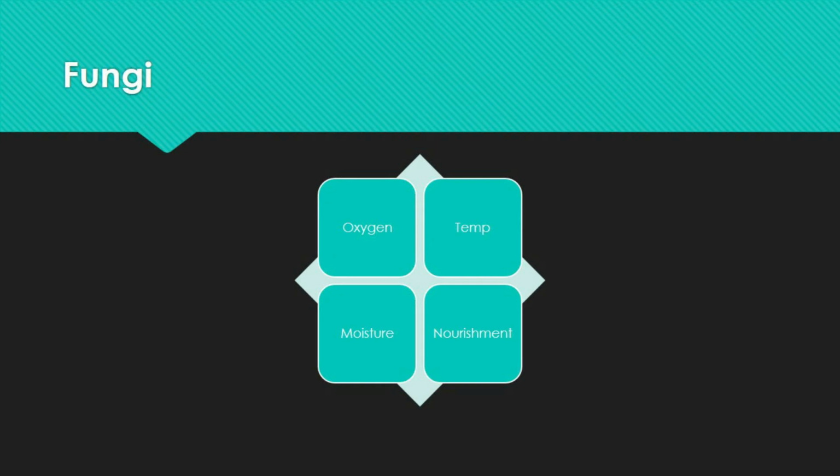Now, these situations are most common where the pole comes into touch with the ground, and to a lesser extent at the pole's top. At the ground line, the infection can begin inside the pole and work its way out, or it might begin on the surface and make its way to the core. And in the latter, we call this the external decay.